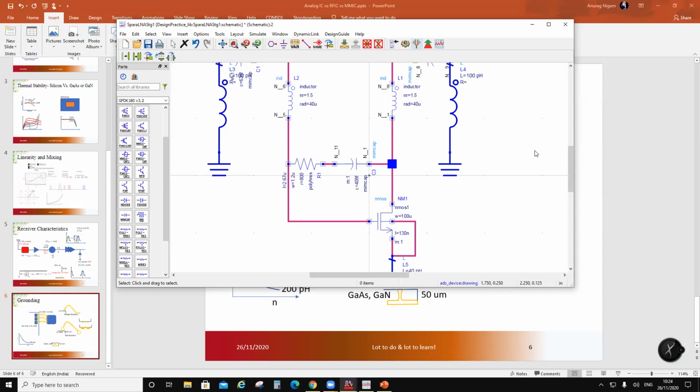They will make a capacitor which is boot shaped. When I see that in layout, I am horrified. I look at their face. When you make a rectangular capacitor, have you simulated currents on a capacitor? Do you know where the capacitor fails? The capacitor fails on the corners. And why does it fail on the corners? Because all the current is crowded at the corner. If you make a square, then the current density on the corners is less.